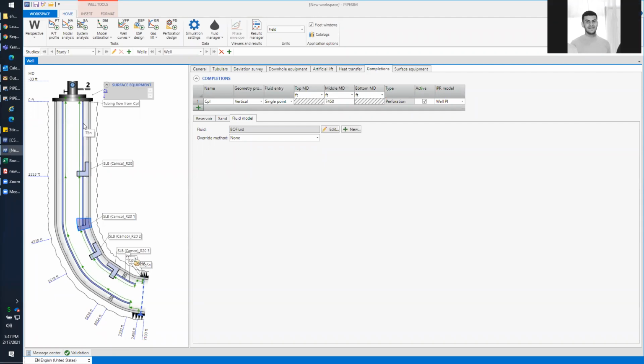I see. So the implementation of this simulation is done through the GOR. It is actually both. It will calculate how much is the free gas. For example, if the GOR is 250, maybe it is still above the bubble point, so all that will be liquid. Now once we inject, here we are injecting 1.5 million, it will take the gas flow and mix it with the oil, and then find how much will be free gas and how much will be dissolved. All that will be taken into consideration while it calculates the pressure drop along the wellbore.